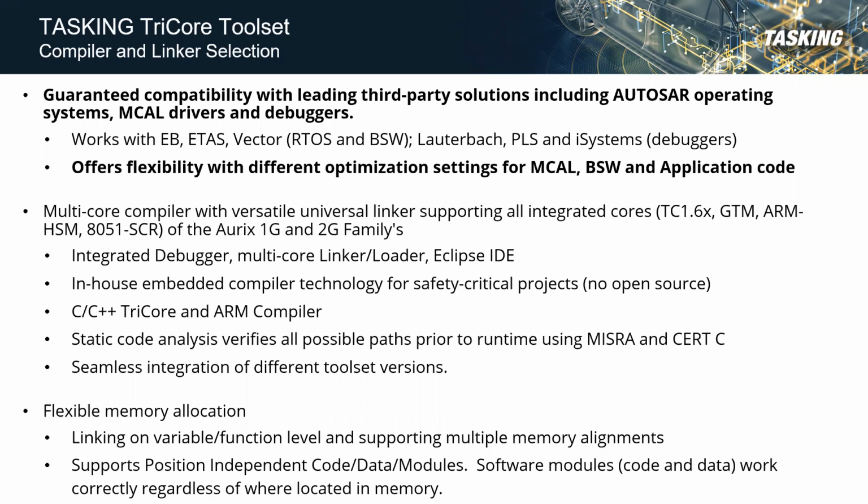Cross-compiling as Tasking supports it allows you to compile legacy code with newer tool set versions, and it allows you to take advantage, say, of some of the newer features that are in version 6.3, and still be able to utilize Infineon MCAL version 6.2 R2 with only one out file and using only one IDE.